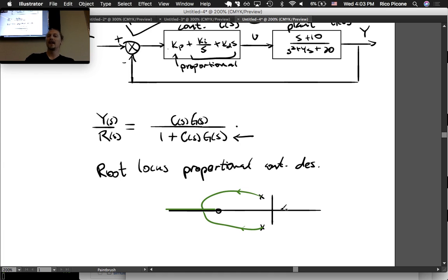We increase the gain, and in fact, it never goes unstable either. So I just happened to pick a system that works out pretty well in that regard. Wasn't a totally naive decision on my part. Anyway, so that's closed loop pole locations. They moved leftward. We're interested to find a gain that has a response that we want.